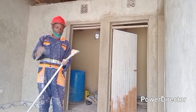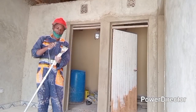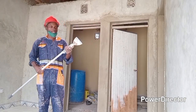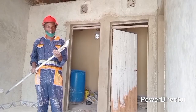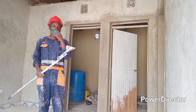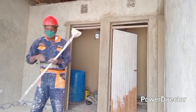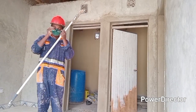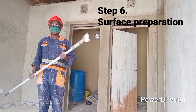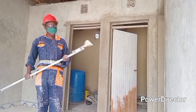First of all, we have to tie this scraper on this aluminum rod like this. After tying it, make sure it is rigid enough to do the work. Then we put on this mask because it involves a lot of dust, and then put on the goggles. Now we are ready to start the work of surface preparation, and we are going to start with the scraping. Now let us start.